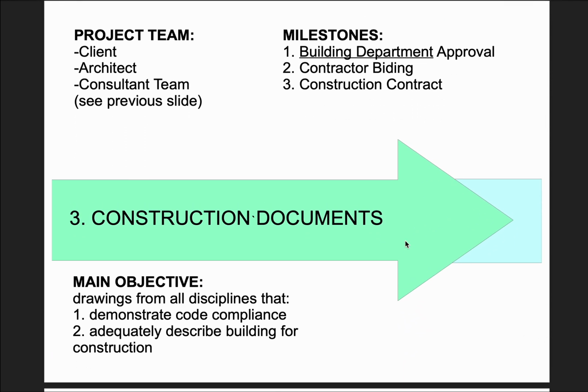The next phase is construction documents, where you're going to put in a title block, dimensions, notes, legends of walls and assigning them ratings, making sure that you've satisfied code in terms of hallway widths, location of windows, how wide the windows are. So all of your teams are involved, and the main objective of construction documents, because you're going to present this to the building department, is that you are meeting code, and your building is physically capable of being constructed.